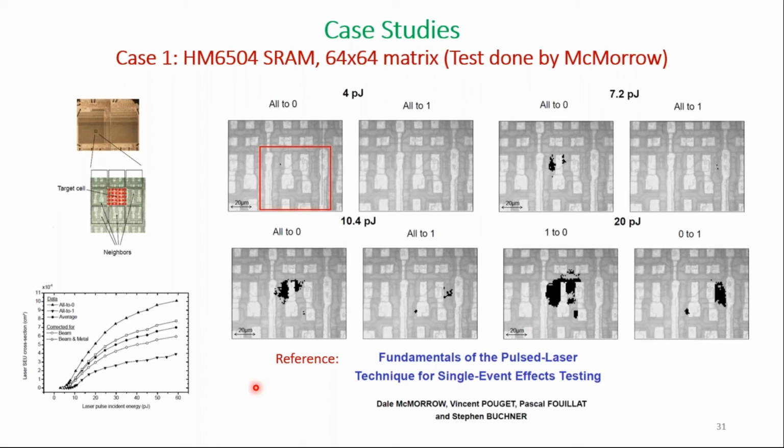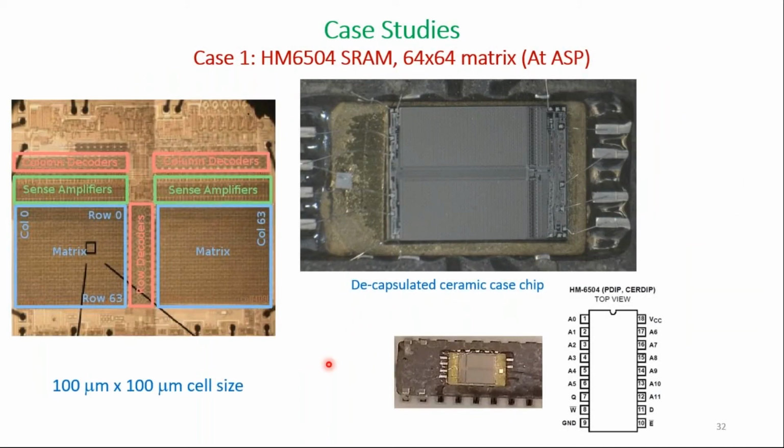So we tried to replicate this test with our laser, which was different from their laser at 1030 nanometer. So the first thing was to decapsulate the chip. So we got a hold of a ceramic case chip, which is easily decapsulated.